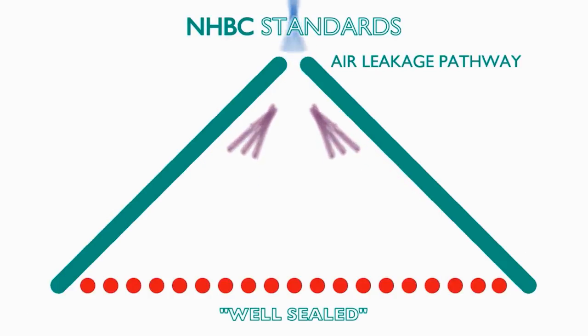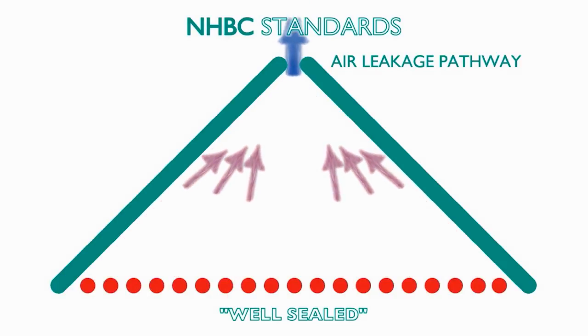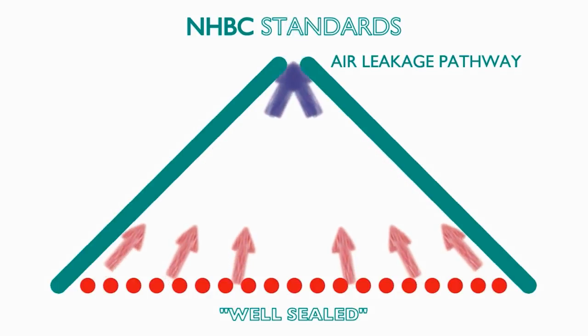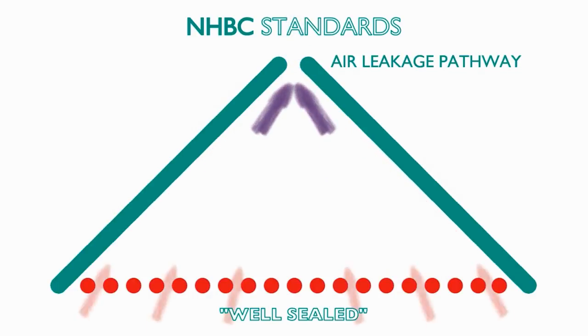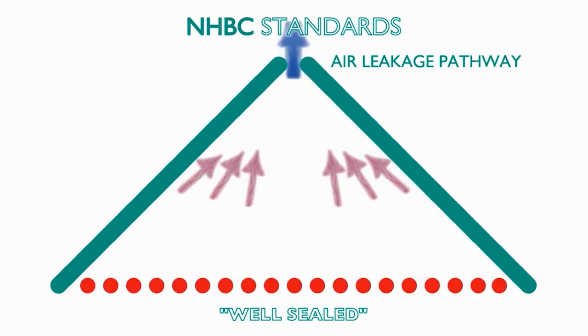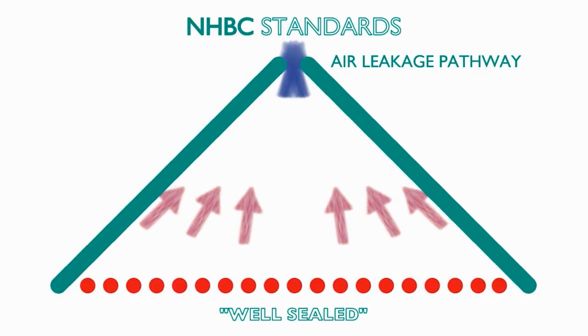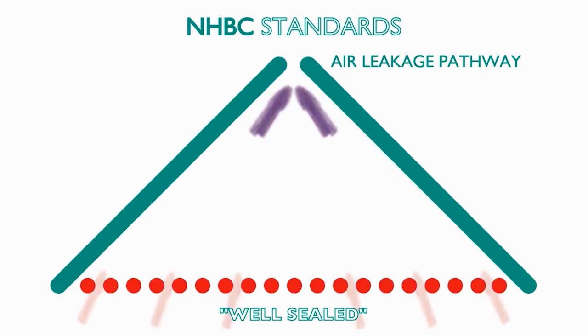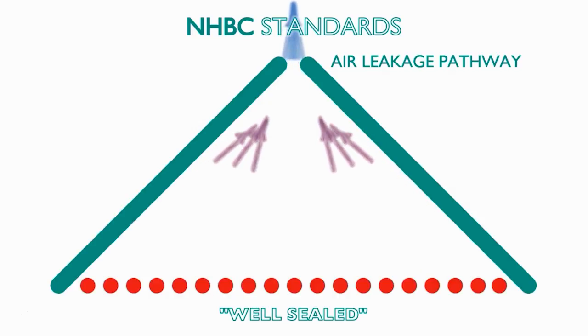Finally, this gap means that the roof is not airtight, negating the energy performance benefits used as a selling point by the airtight underlay manufacturers. It also places a lot of emphasis on the quality of the ceiling installation, which can be an issue if electricians, plumbers, ventilation installers, etc. are not aware of the specific requirements of BS 9250.